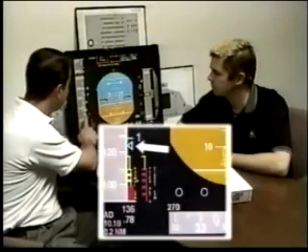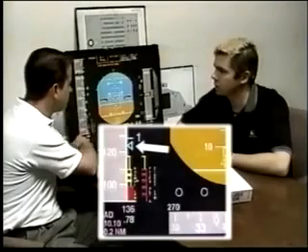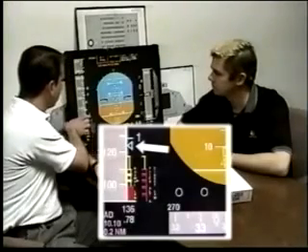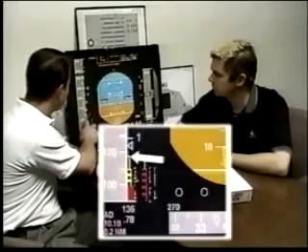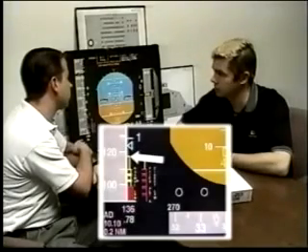Okay. Is that always displayed then? No. It'll display anytime acceleration is greater than 2 knots per second, and it disappears when acceleration is less than 1 knot per second. Now we have a blue speed bug. What type of speed is that? That's a selected speed. Okay. And what would be that blue one? That's V1. The top block of our amber portion is called what? VLS. Okay, and VLS is what? That's V is speed, so V lowest selectable.